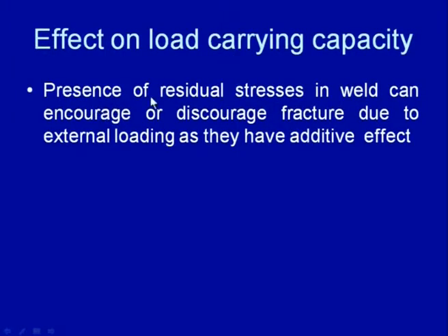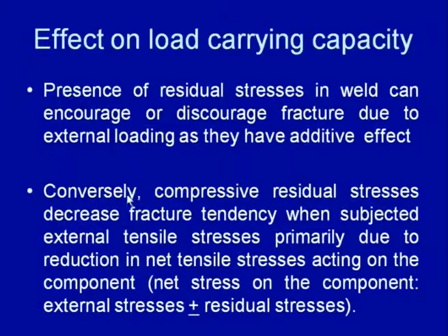So, the first effect is that the load carrying capacity of the weld joint is affected by the residual stresses. We know that the presence of residual stresses in the weld joint can increase or decrease the fracture tendency due to the external loading, as they have an additive effect. It means if residual stresses of tensile nature are present, then the component will tend to fail earlier under tensile external load conditions, but the performance of the component will improve under compressive loading conditions because of their additive effect. Conversely, the compressive residual stresses decrease the fracture tendency when the component is subjected to tensile stresses,